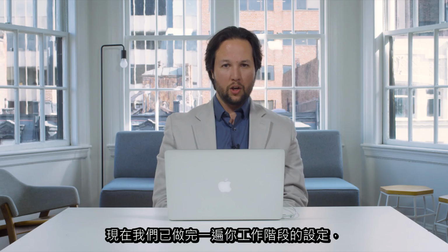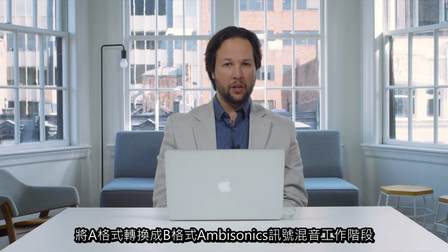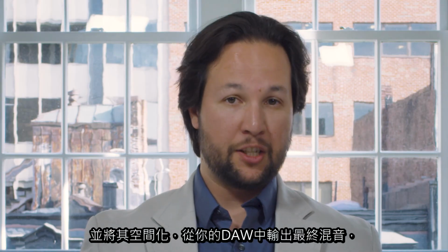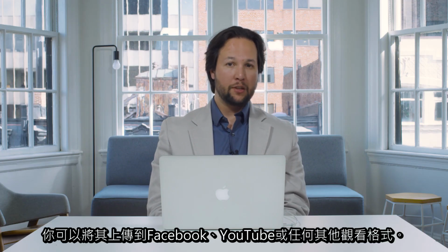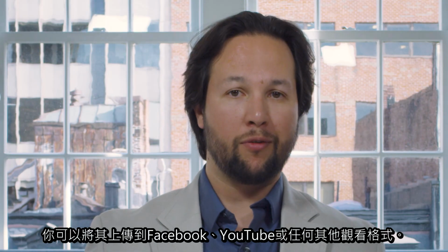So now that we've gone through setting up your session, converting A to B format ambisonics, mixing your session and spatializing it, outputting that mix out of your DAW, and encoding it into a final video, you're ready to upload that to Facebook, YouTube, or any other viewer format.